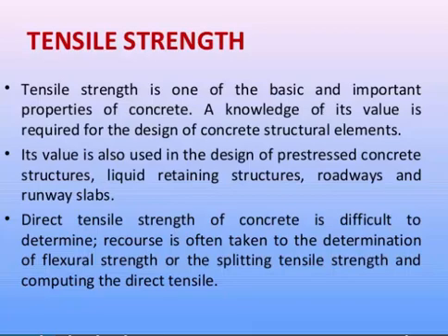So the split tensile value is very important in the designing of these structures, retaining structures and roadways, which are adjusting the loads, and based upon the split tensile strength of the concrete, the structural design elements are taken into consideration. So the tensile strength is an important property of the concrete.